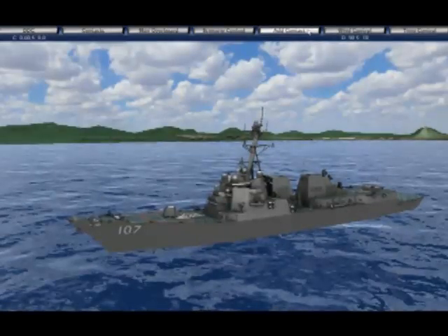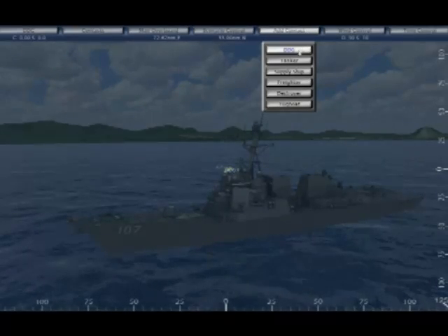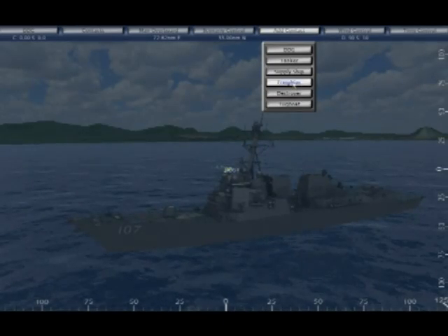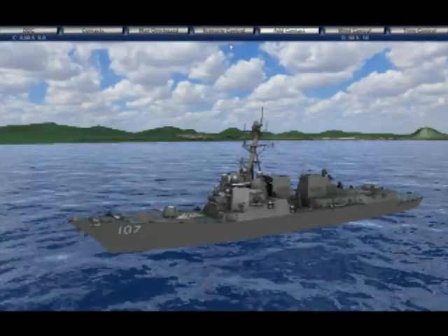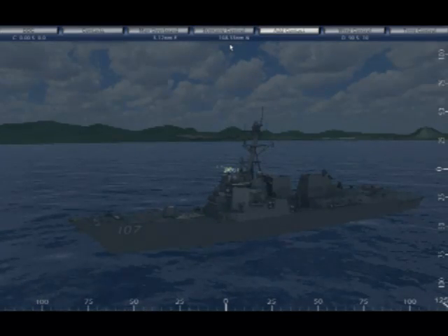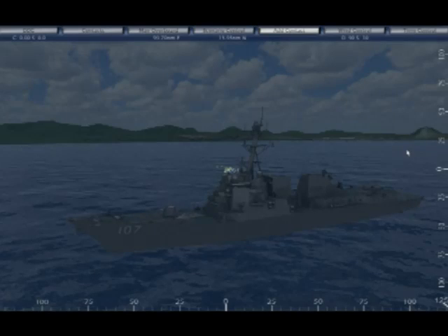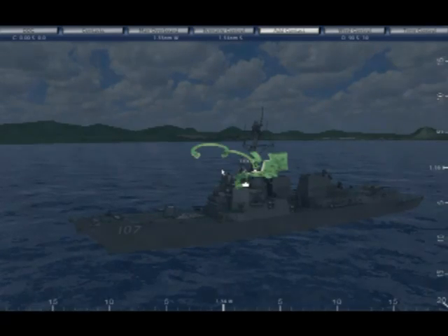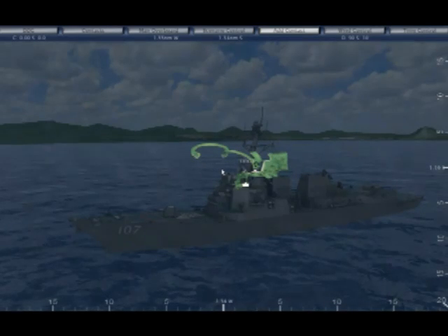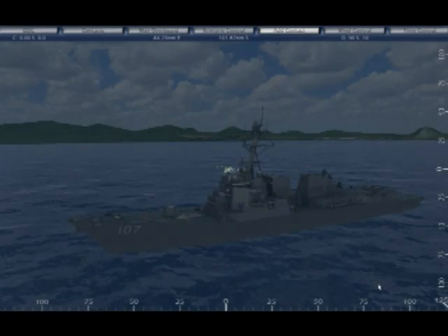Next, go to the Add Contacts menu. Once this menu is accessed, a top-down view of the WaveLore environment will appear. This is called the Scene Map view. This view can also be accessed by pressing the Tab key. There are two zoom levels. Level 1 is 40 by 40 nautical miles, Level 2 is 4 by 4 nautical miles, and if clicked a third time it will snap back to the original 250 by 250 nautical miles.